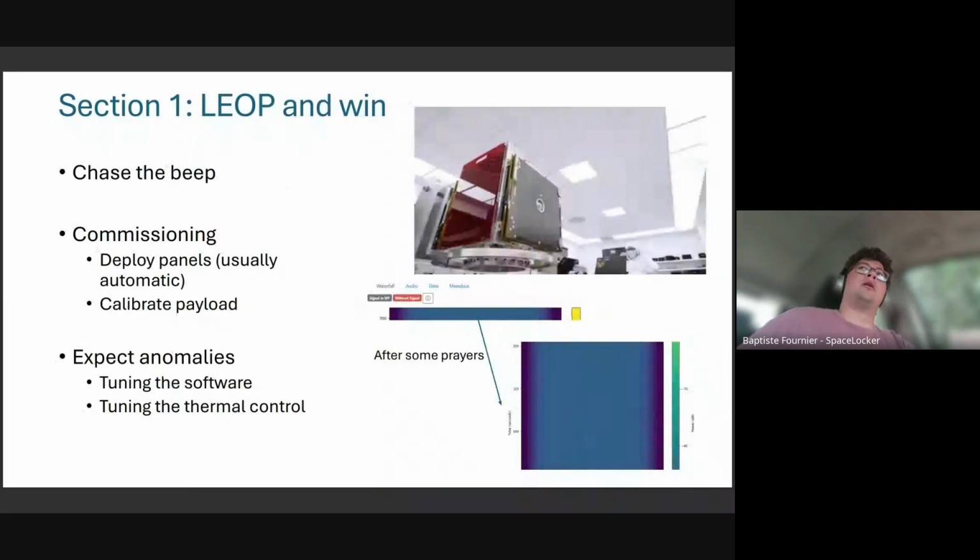It depends a lot. Because you need to telecommand your satellite, you have an uplink, a ground to space radio link. Within the telecommands, you can have telecommands that change parameters in the software. So this is one way of tuning how the software works, because you can have somewhere in the software a line that compares a temperature with a set point, and then you can program in your software, when you're on the ground, a telecommand to change that set point.